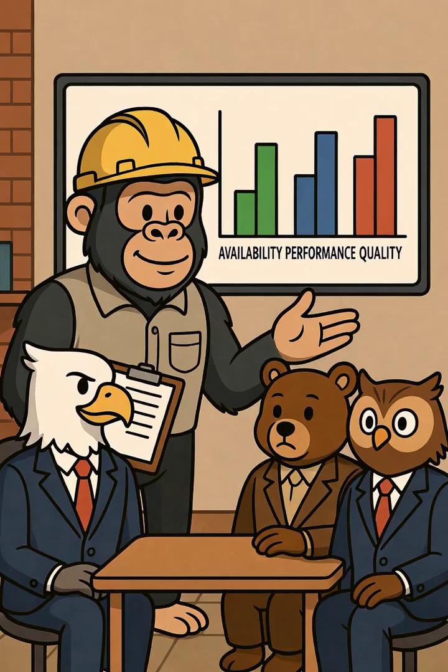So how do managers actually use OEE in the real world? First, as a diagnostic tool, if your OEE is low, you can immediately see which of the 3 factors is the biggest problem. Is it availability? Then focus on reducing downtime. Fix those breakdowns, speed up changeovers, eliminate waiting. Is it performance? Then investigate speed losses. Clean your sensors, maintain your equipment, train your operators. Is it quality? Then dive into root causes of defects. Check your materials, calibrate your machines, improve your processes.